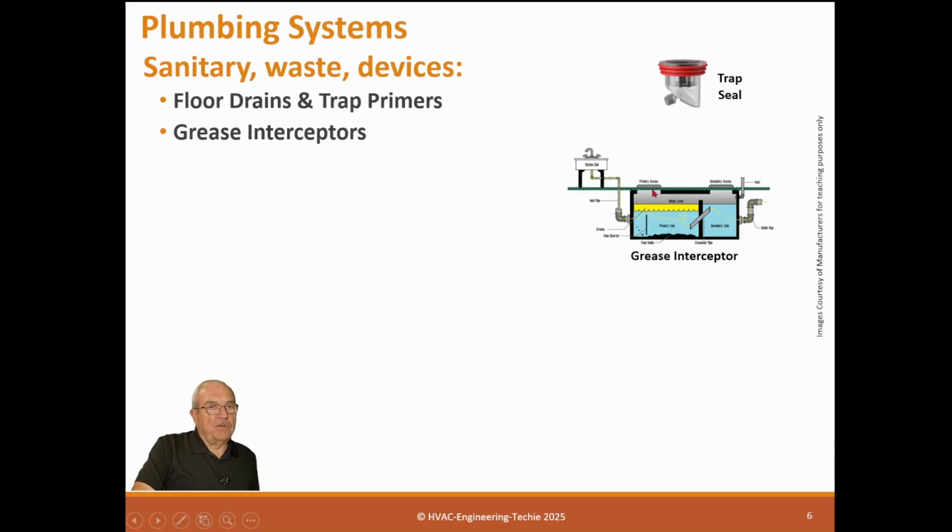And periodically you pump this out and clean it, and that way it doesn't allow any oil or grease to get into the system. And of course, this is a code-driven requirement for anybody who has a kitchen or anything that might induce oil or grease into the sewer system.